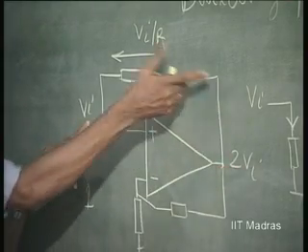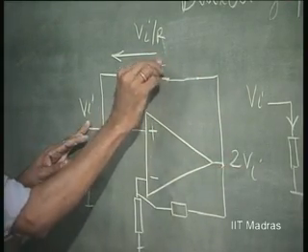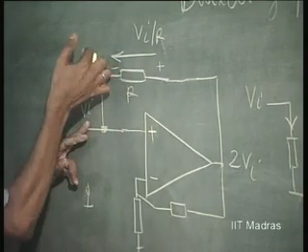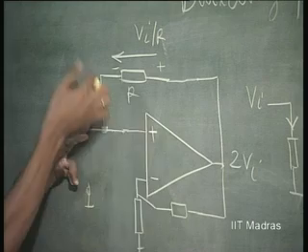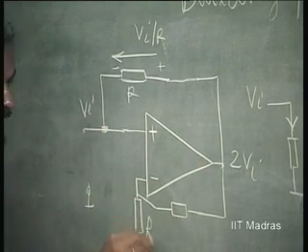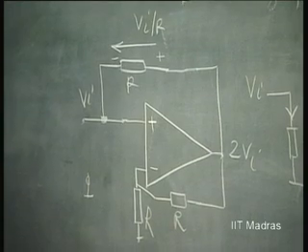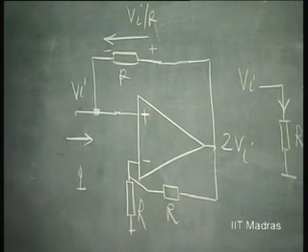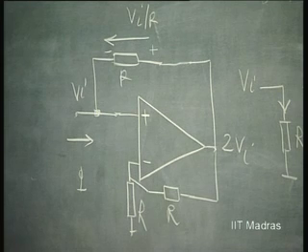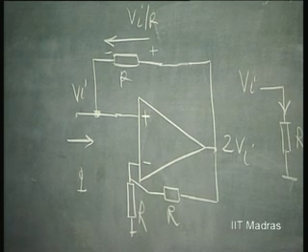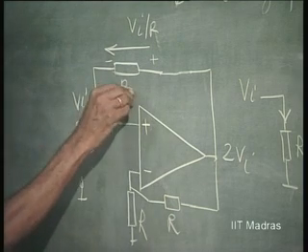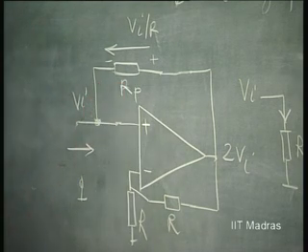So, the potential difference here is going to be plus here, minus here, of Vi, and the current will be Vi by R in this direction. So, how do I get a gain of 2? I can put R and R. So, this simulates a negative resistance of magnitude R. I want to simulate a negative resistance of magnitude Rp, so I simply put here Rp.